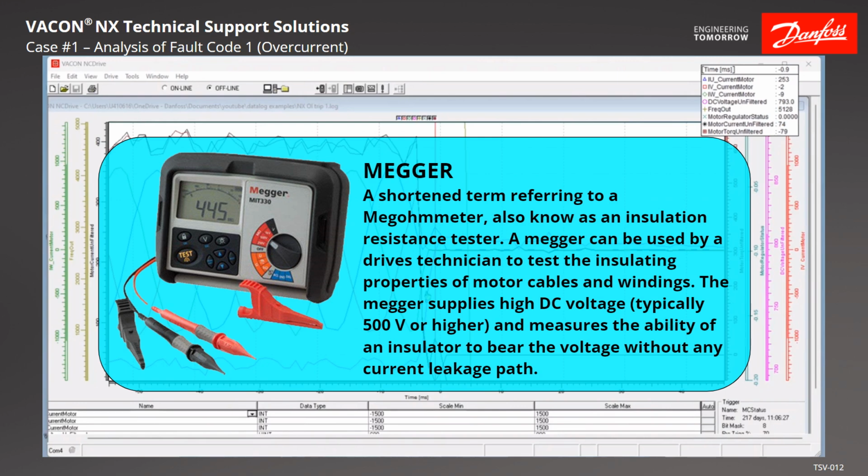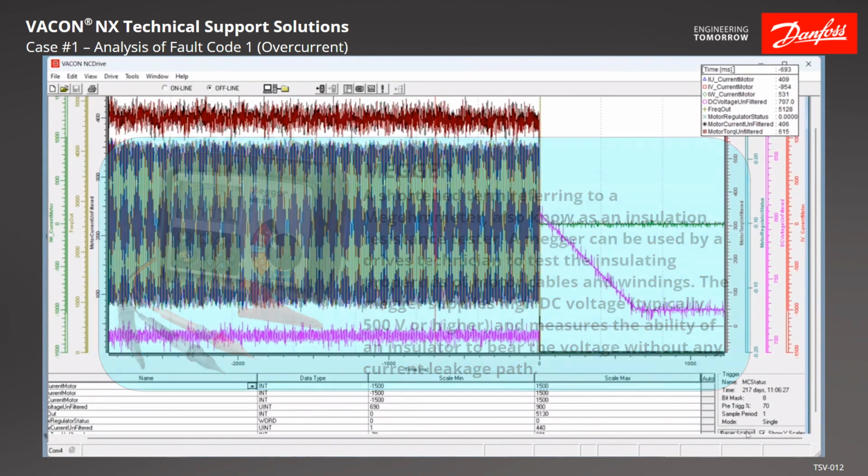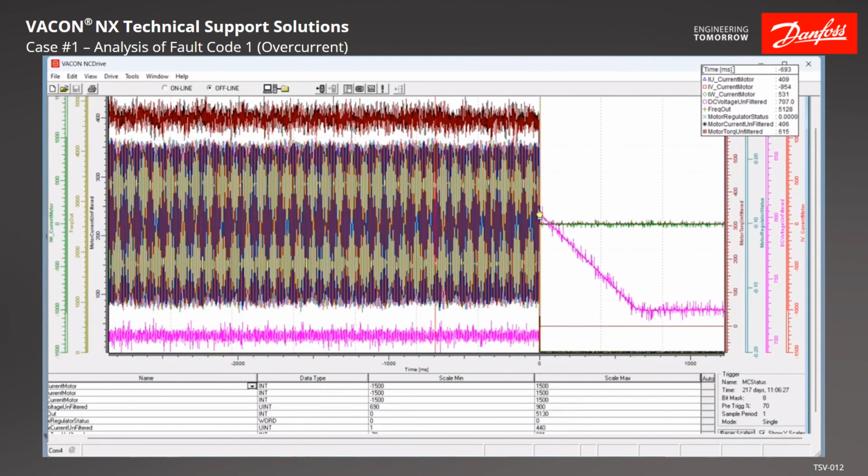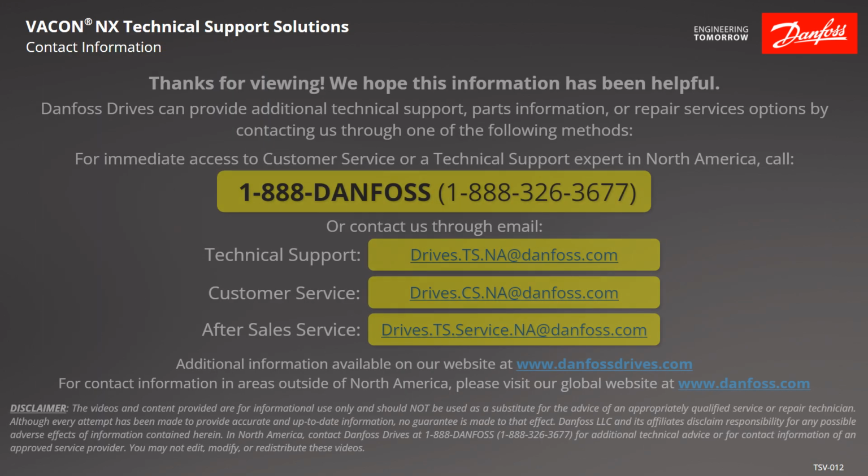Because we can somewhat see, as that DC bus went, if we want to see what happened to DC bus after the trip, let's reset scales, and you'd see the DC bus did jump, and it kind of discharged back down again here. So that means that we got a pretty good spike in current. And when it goes to ground on the output, it wants to change the ground reference and kind of rectify that back in the front end of the drive, and you get that spike in voltage on the DC bus of the drive.